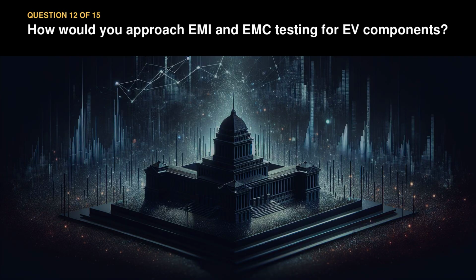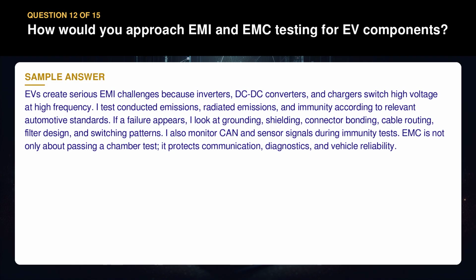Question 12. How would you approach EMI and EMC testing for EV components? EVs create serious EMI challenges because inverters, DC-DC converters, and chargers switch high voltage at high frequency. I test conducted emissions, radiated emissions, and immunity according to relevant automotive standards. If a failure appears, I look at grounding, shielding, connector bonding, cable routing, filter design, and switching patterns. I also monitor CAN and sensor signals during immunity tests.